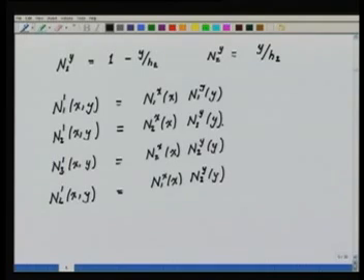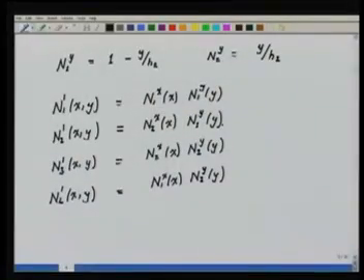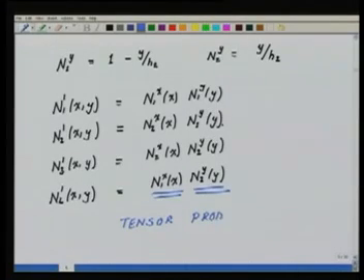Okay. So I have defined these 4 shape functions with respect to the 4 vertices of the rectangle, and this is the minimum we can do, because these functions have to be defined by the logic that we have been following with respect to these 4 vertices. Now you see that these are by definition products of functions in the x direction and functions in the y direction. Since they are defined as products of 1D functions defined in the x and y direction, they are said to be the tensor product family of shape functions.